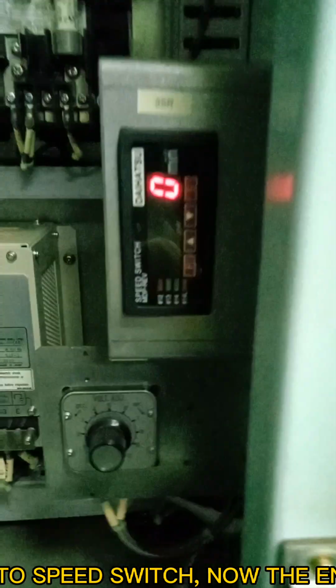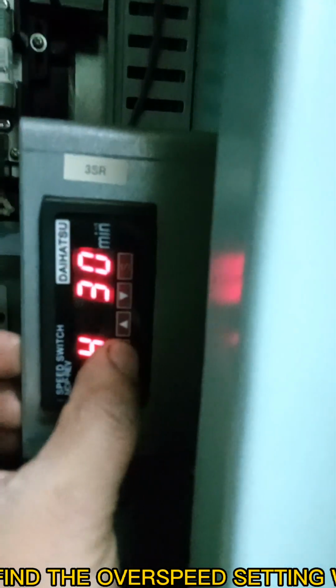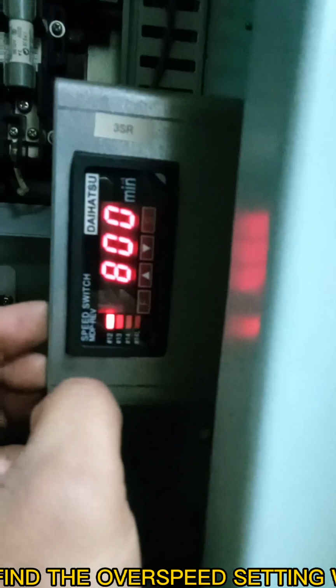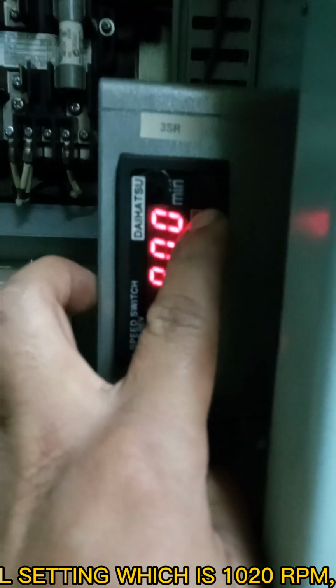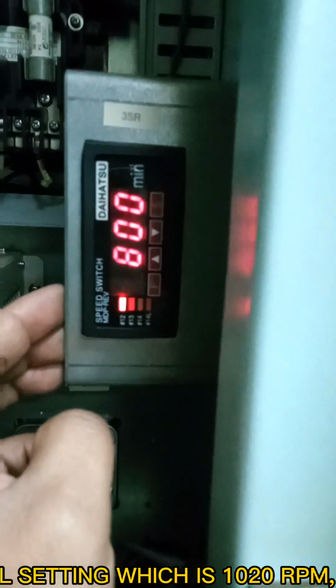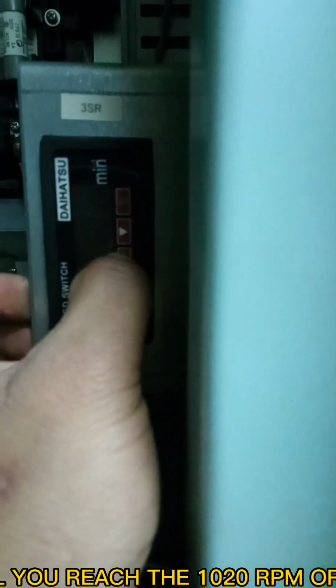Now the engine is at stop position and the current RPM is 0. Reverse the procedure to reset. Press the F key to scroll until you find the overspeed setting we changed, which is from 1020 to 800 RPM. Press the S key so that we can change the setting back to the original setting, which is 1020 RPM. When the figure flickers, this means you can now change the setting. Press the arrow up key until you reach the 1020 RPM original setting of the overspeed trip.